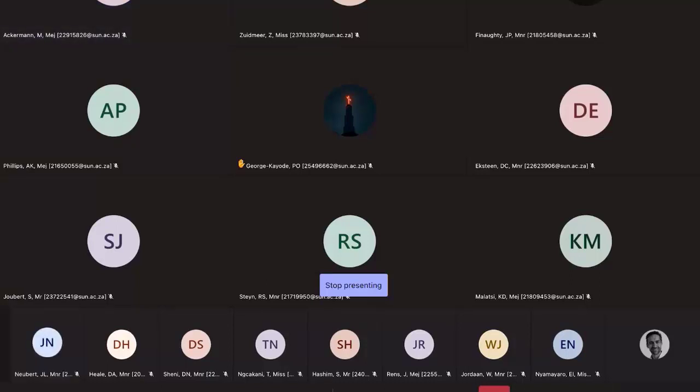So the way that I've designed mine, and I guess it's up to discussion whether my method is the best method to do it, I've designed it such that after it's transmitted the stop bit, it goes back into the idle state, and only then does it go back into the transmission state when the transmit is high. So there will be a clock cycle in between the two nibbles. Is that what you mean?